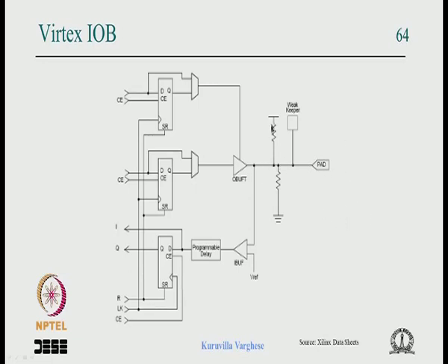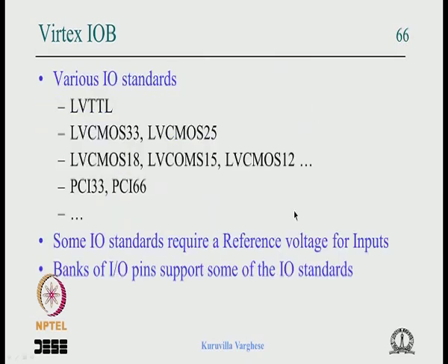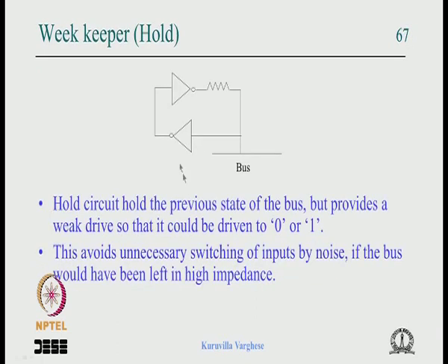So that can be avoided through a large pull-up and large pull-down, or you can program a whole circuit which weakly holds on to the last value, to avoid noise pickup. And it supports various IO standards, and this is a whole circuit.